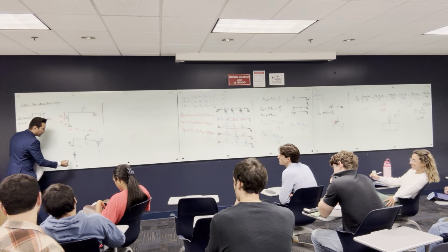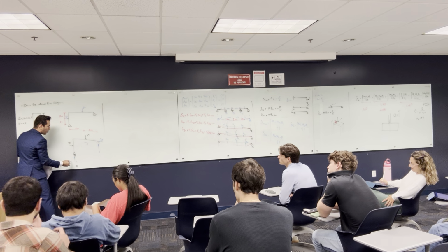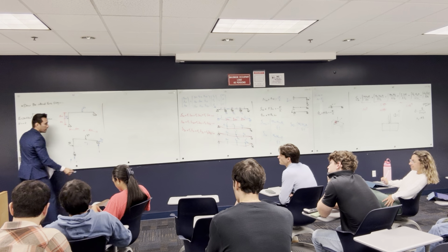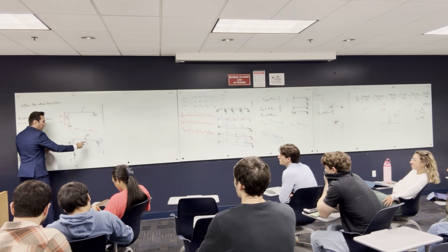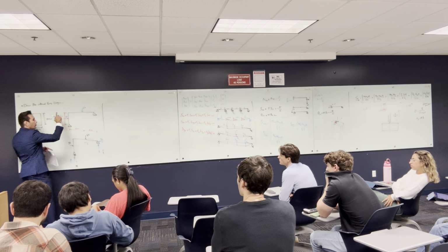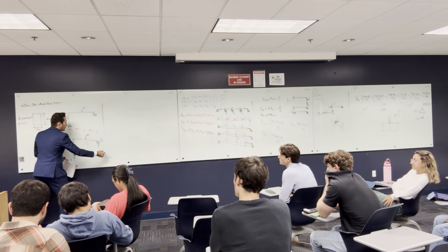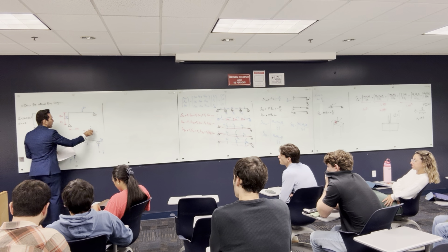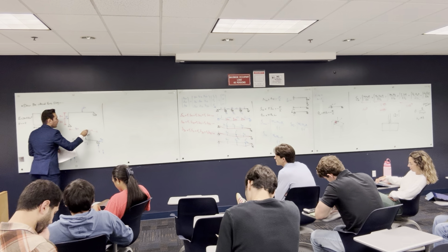So you need a moment, this is going to make that way. I believe you are going to have a reaction here and another one here that counter this moment. So 3 multiplied by 2, 6 ton-meter. You need another 6 ton-meter that counters the moment here. Is that 6? This is 3. So 3 meter and 3 meter.